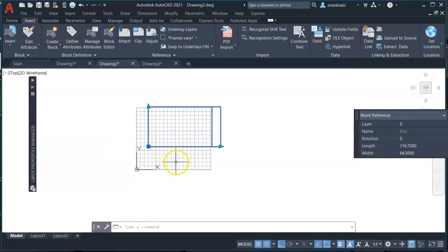There are other actions as well that we can make to a dynamic block to adapt. Imagine this feature can be applied to many things, like windows or doors in architecture. You can create one block, and make different sizes of doors with one dynamic block.